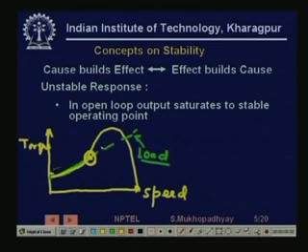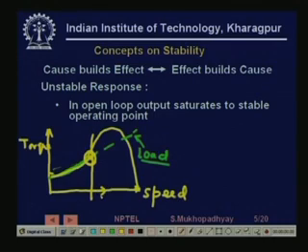So, it's a stable operating point, the motor is generating enough torque which the load demands. But if the speed here is slightly changed, let us say this way, and the motor goes to this position, then the generated torque, which is this one, is more than the load torque which is given by the green curve.